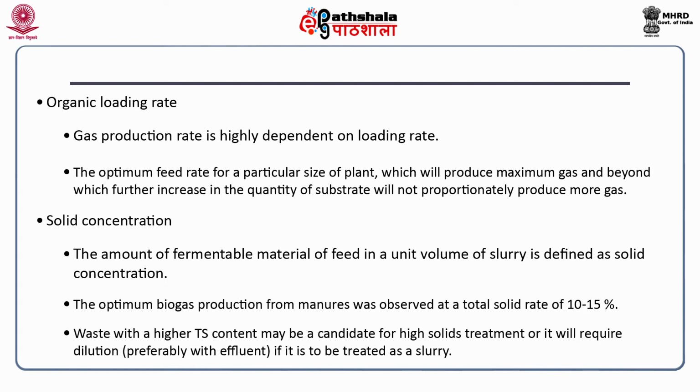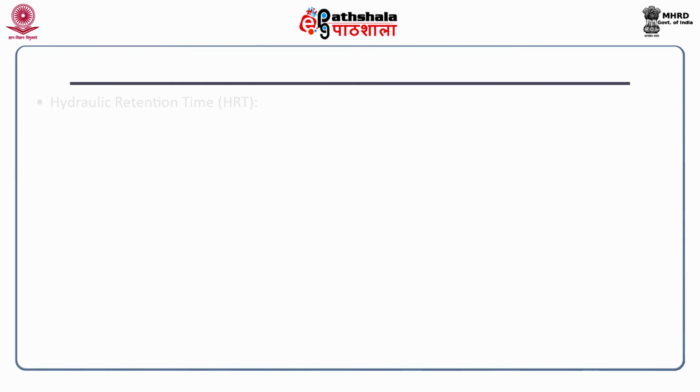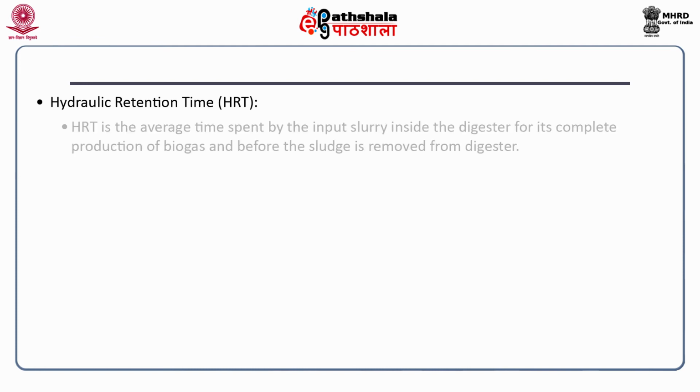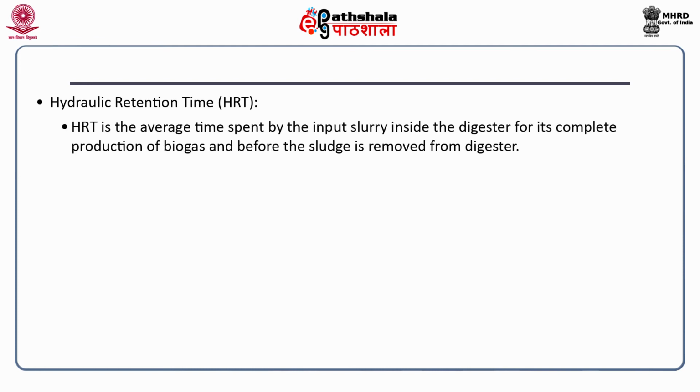So, the total solid rate should be taken care of while using it for biogas production. Now, HRT, or the hydraulic retention time, is the average time spent by the input slurry inside the digester for its complete production of biogas, before the sludge is removed from the digester.